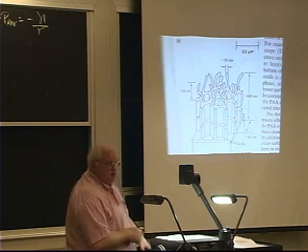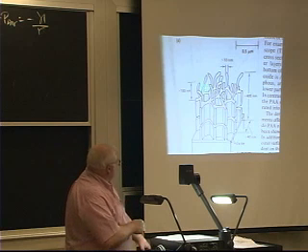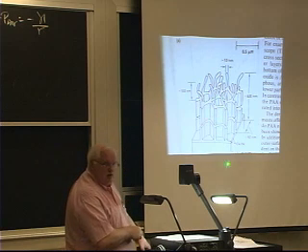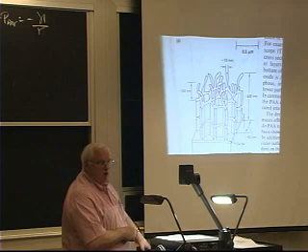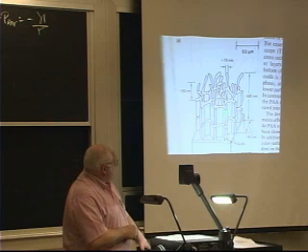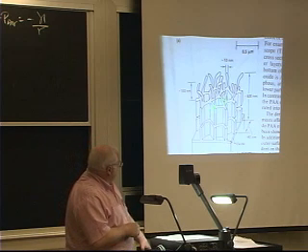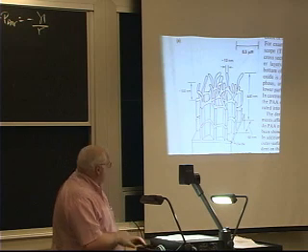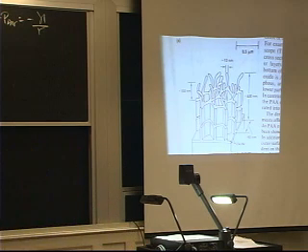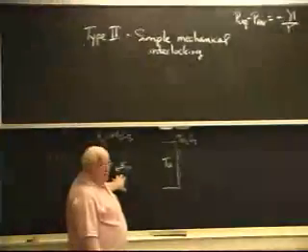this is the very rough surface. But if I want corrosion resistance, I don't want something that's going to allow the electrons to get in here and keep the corrosion process going. So after I anodize something, I have to seal it. Sealing it means that you turn the current off, and typically the electrolyte you might use for anodizing aluminum might be sulfuric acid.